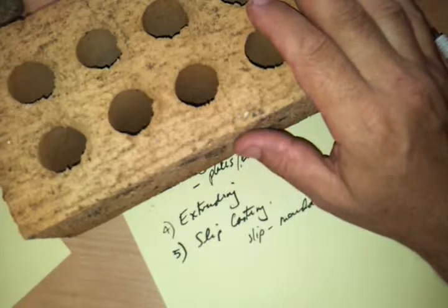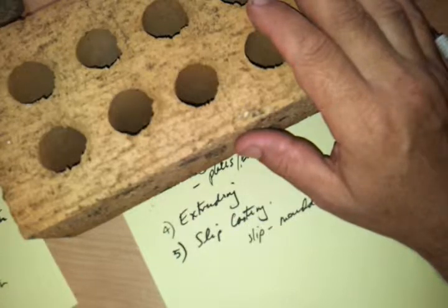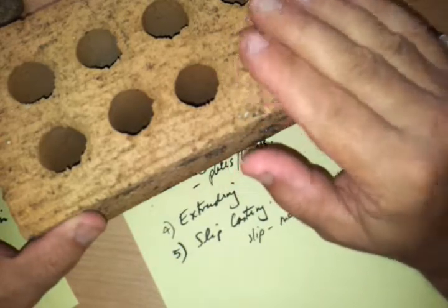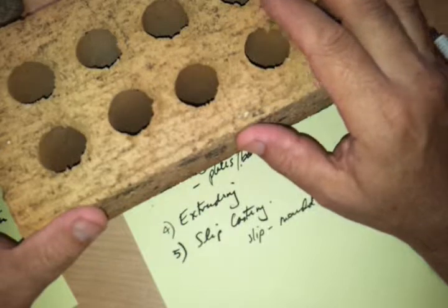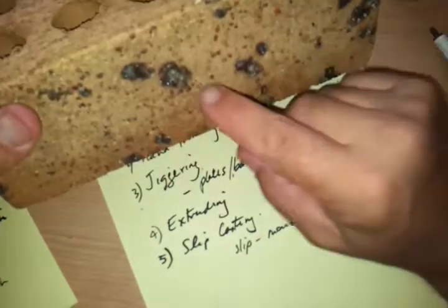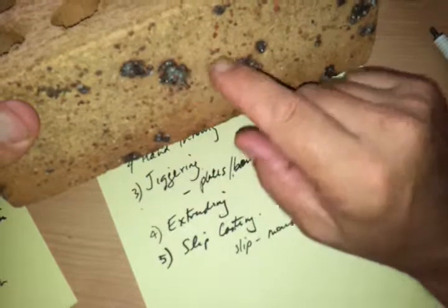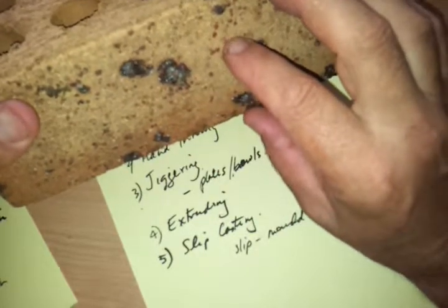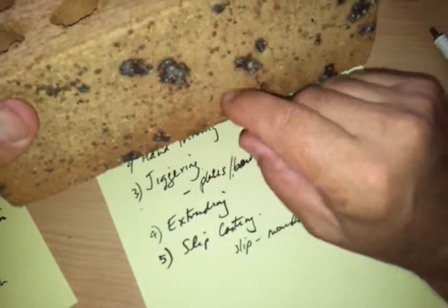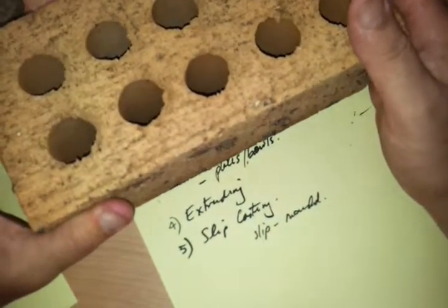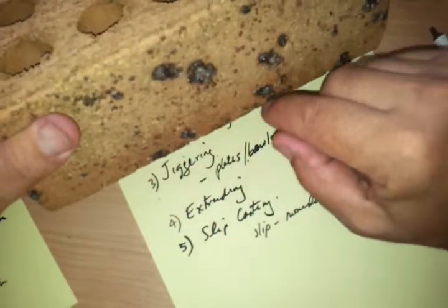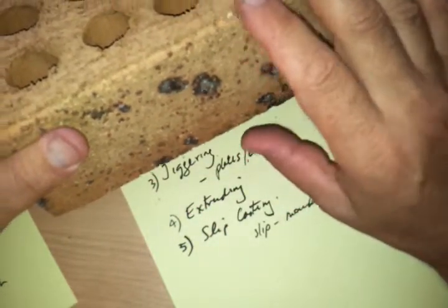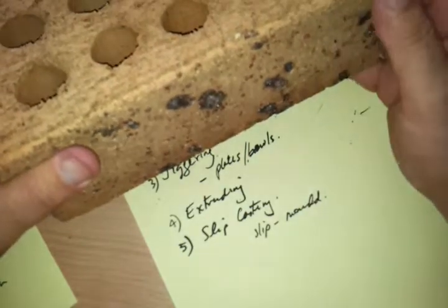Okay, now the bricks that you see over here, this was extruded, and we spoke about bricks being able to be pressed as well, and they're fired at the earthenware type of temperatures. Some kind of additives can be put in to create different effects, and metal oxides are used to colour the bricks as well. And you can see there's a number of different items inside these bricks. So again, the properties of bricks: very strong in compression, weak in tension. Mortar is used in between them to be able to transfer forces from one brick to another evenly without creating stress points.